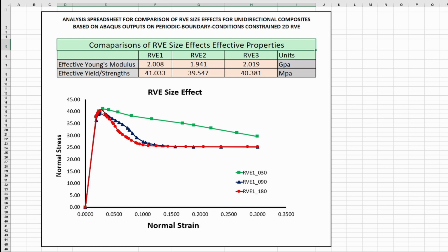What is particularly important and different when the RVE size become important is what's happening in the post-yield response in this region. So clearly for the smaller RVE size, it's not capturing this significant stress softening that we see here. And even in the plateau stress, where everything kind of averages, it's not capturing, so it continues to decrease on and on and on. So there, clearly the energy dissipation for the RVE size is not as significant as you would expect for the bigger RVE size.